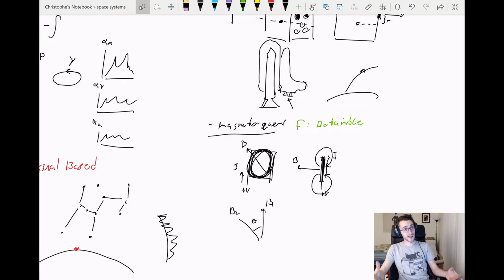The downside is that they generate significant magnetic fields within your space vehicle. Depending on if you've got large currents or other components that use large currents running through your space vehicle, that might damage some electrical equipment on board, or it might mess up your sensors. Remember before, if we have magnetometers on board and we are trying to measure the Earth's magnetic field, it's really hard to hear someone whispering to you in the middle of a rock concert, right?